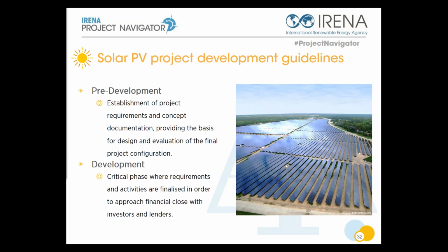So in those guidelines, you will find what is the structure of a contract, what is the scope of work, how do I draft the technical specification, what are the traditional milestones and completion dates, how do I structure my price and how do I pay my contractor based on progress? How do I prepare acceptance procedures and provide guarantees that are commensurate to the size of the project? And how do I prepare the negotiation for liquidated damages, project bonds, and so on? That will be an important piece of documentation that will be required to close your project.